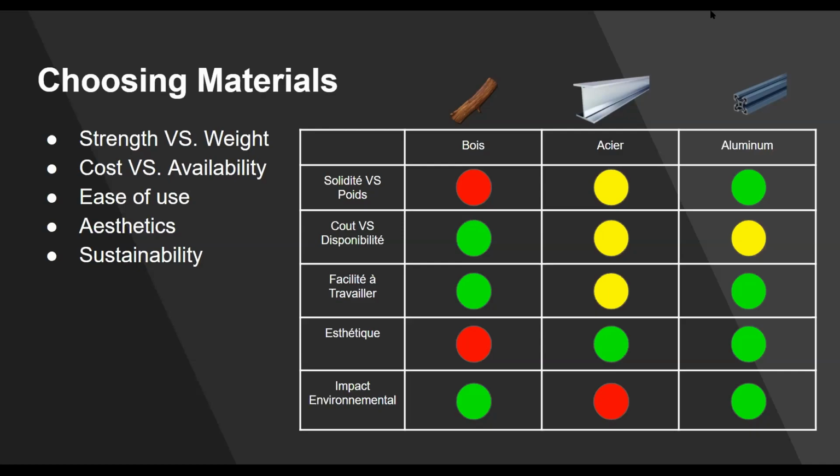So then we get into our big boy, good old steel pipes and things like that. Those are aesthetically very pleasing, makes your robot look very fine-tuned, very polished. It's not as easy to work with, but it's a lot stronger. So those are the things that, especially for a frame, you might consider using. It's a lot easier to weld than something like aluminum because it makes really good joints. So it is something to consider when you're going for something that's very, very sturdy, but it's not the easiest thing to work with if you're newer and it's not as malleable.